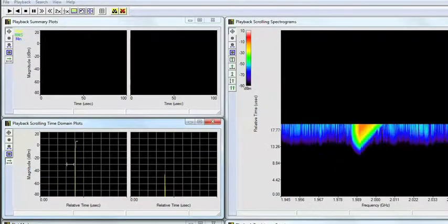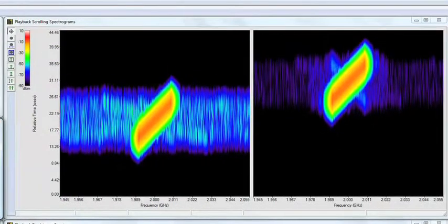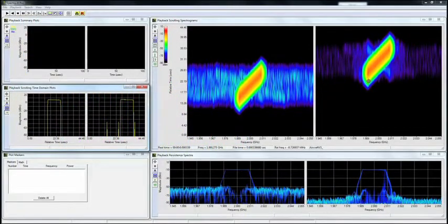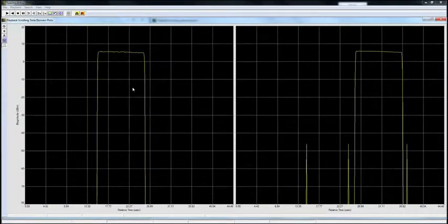But even with that, it's very difficult to know in the frequency domain plots where we would place a particular marker, and then how we would use that marked information to help us make that time difference measurement. So let's return to a pure time and magnitude display, enlarge that to the greatest extent that we can across the monitor, and place markers at equivalent power levels.